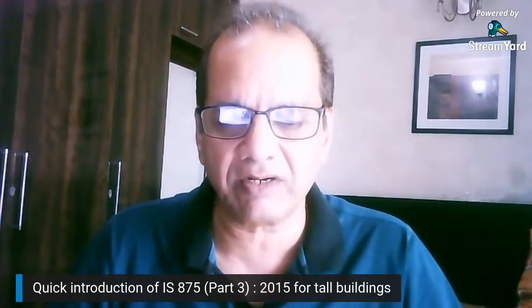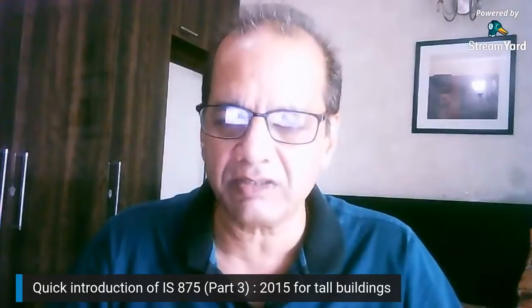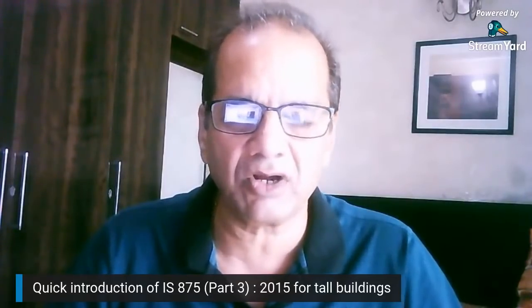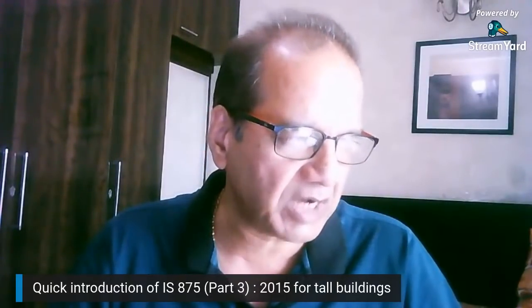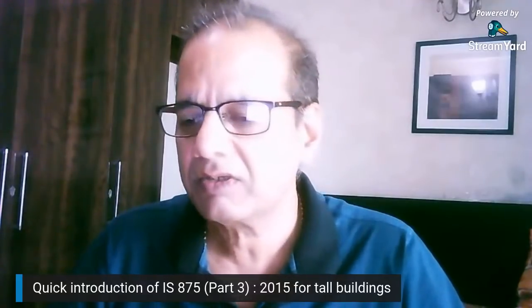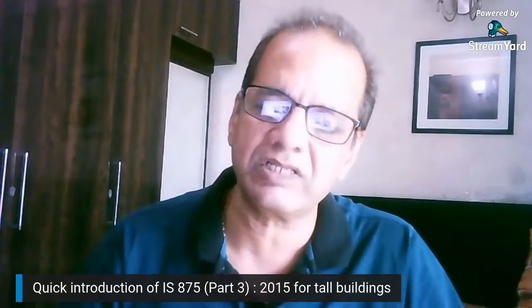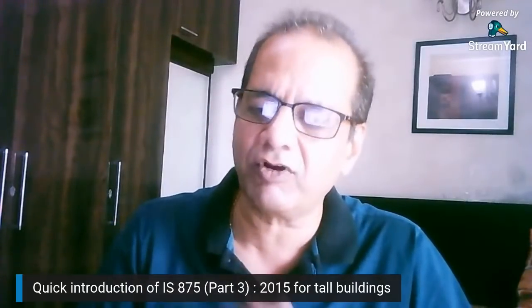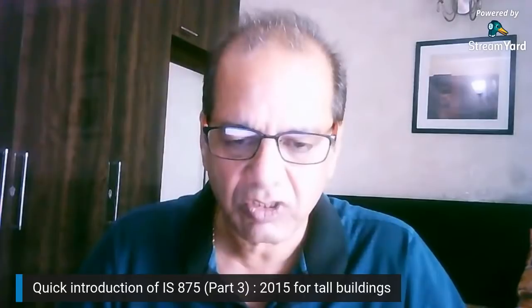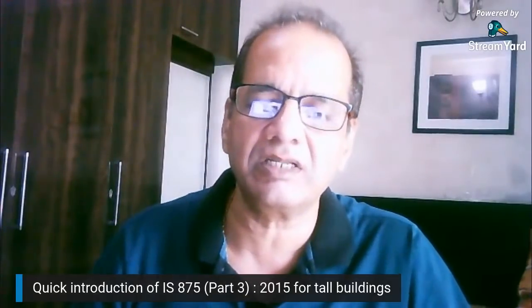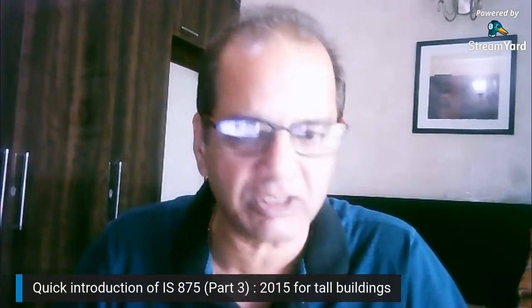Why is it called Gust Factor approach? Because in the tall buildings, the response is comprising of two parts. One is a static part and one is a dynamic part. The dynamic part is primarily calculated using the Gust Factor. What is that? We'll discuss more. So moving ahead from the Gust Factor approach, now recently the crosswind response has been introduced.